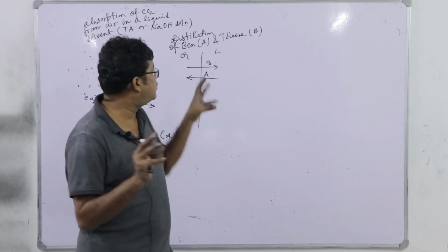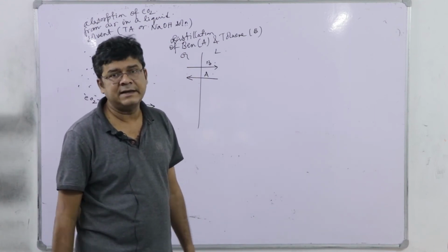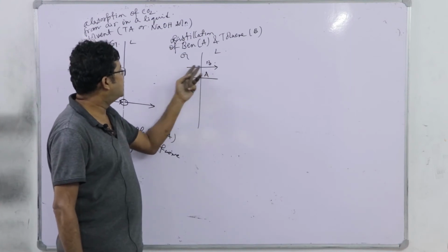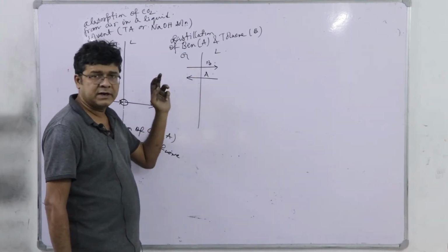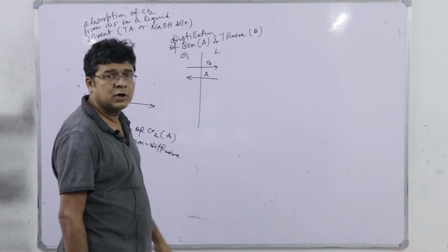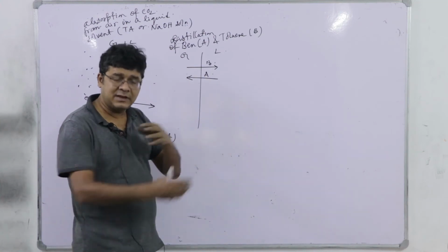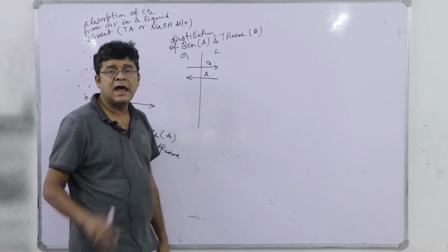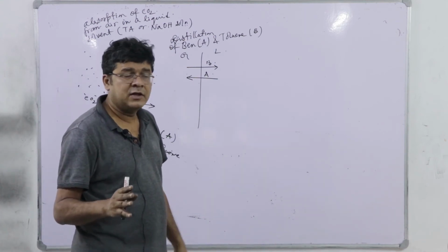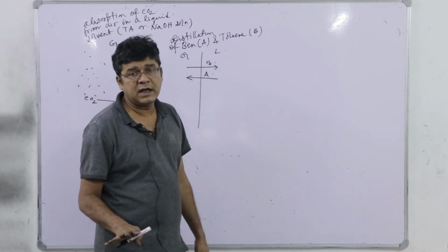If the two components are members of the homologous series, which has similar properties like latent heat, then the latent heat released because of the liquefaction of a vapor component will be just used to vaporize the same amount of liquid component into gas. So, delta Na and delta Nb, the mutual transfer, is nearly equal, and as a consequence we will have the equimolar counter diffusion.